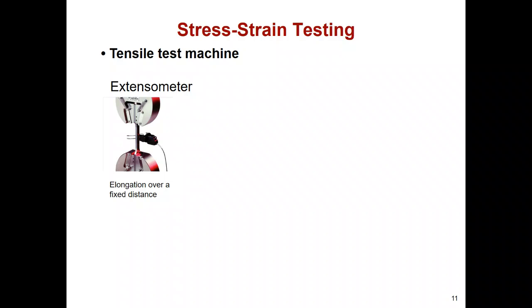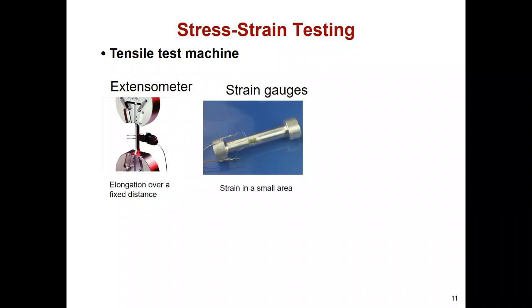To check the stress and strain of a solid material, there are many options. First is the extensometer, and the second is strain gauges. The extensometer can be used several times to detect the deformation. But one problem is that when we apply very large forces, the solid metal will deform too much, and the detecting part can also be damaged. So usually we also use strain gauges.